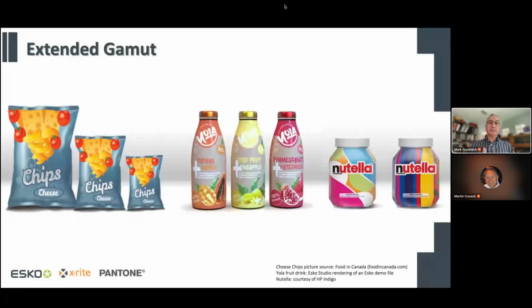A really big thing that's going on more and more now is we're being required to run shorter runs, just-in-time inventories. We don't want to keep a lot of material in inventory. So our print buyers are often requiring us to run more frequent short runs, or you end up having to combine products on the same layouts, especially in offset scenarios, to try to keep down the cost of your make-readies and such. So by having what we call a fixed palette of CMYK, orange, green, violet on the press and not running special Pantone colors with all of our jobs, we can actually leave the same inks on the press, switch out the plates, or run more product on the same plates, and reduce those wash-ups between our productions.